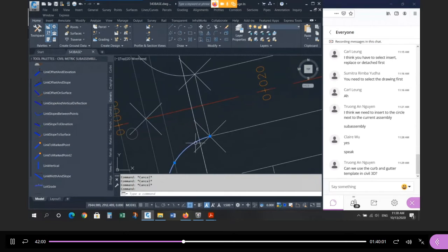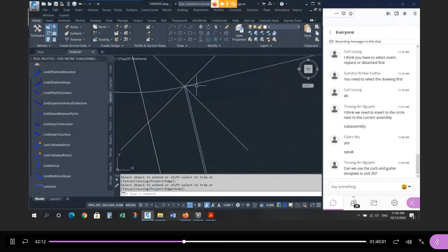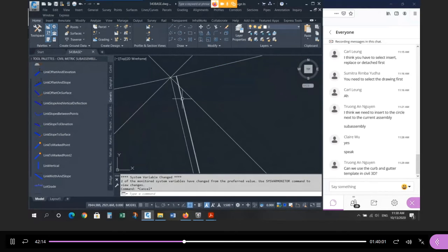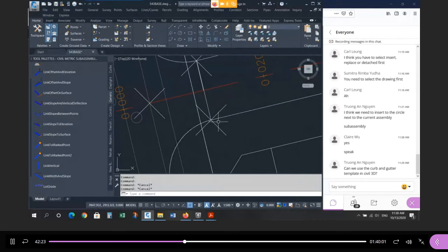Because we're going to need catch basins at the low points. That puts a catch basin on the end of this curve, and then it puts a catch basin across the street, not on the curve, but on the line. So the catch basin station will be there, not here. What we want is to make sure that the catch basin is always on the straight line, so we use the one that's furthest away.